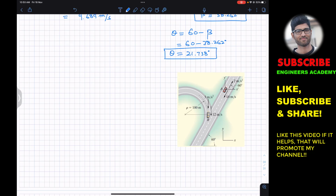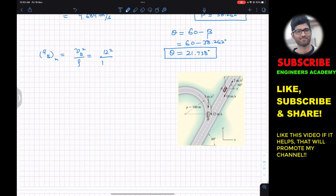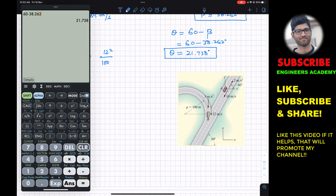As we know, the normal acceleration of car B will be equal to VB square divided by rho. Now VB is known. The velocity of car B is 12 meters per second at this particular instant. So that is 12 square divided by 100, the radius of curvature.